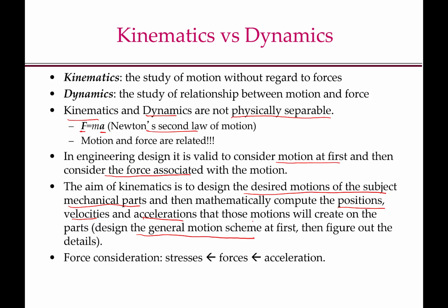Once we have studied the motion, of which acceleration is one output, from the acceleration we can determine the forces required to get that motion, and from the forces we can determine the stresses that will be coming on the parts, which is required for the detailed design part. So the steps are, first we do kinematic analysis, then we do dynamic analysis, and then we do stress analysis. Stress analysis is not a part of this course. We will only do kinematic analysis and dynamic analysis.